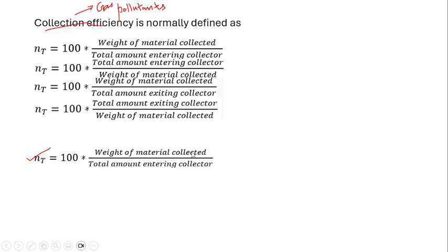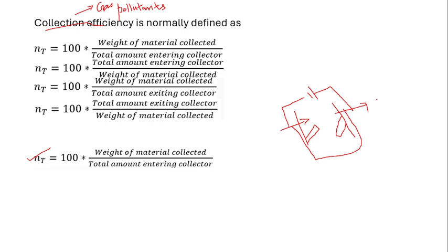In the case of an ESP, which is an electrostatic precipitator, these materials are collected in between the plates. There will be an electrostatic medium. When the gaseous pollutants pass through this electrostatic medium, which is connected to an electric field, the metal rod ionizes the gaseous pollutants.